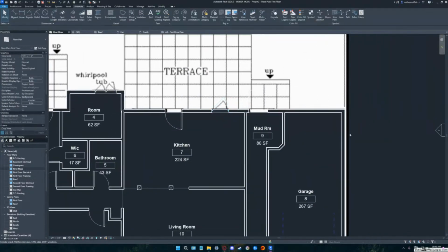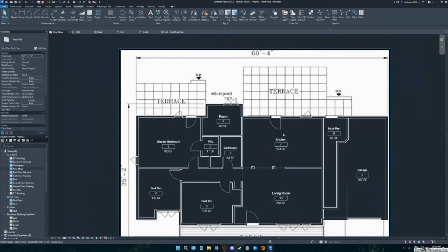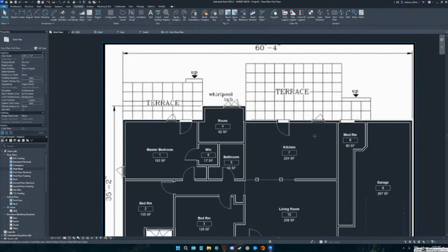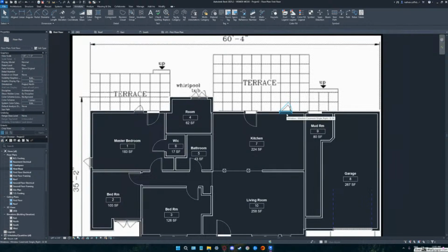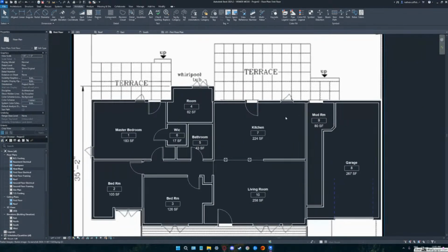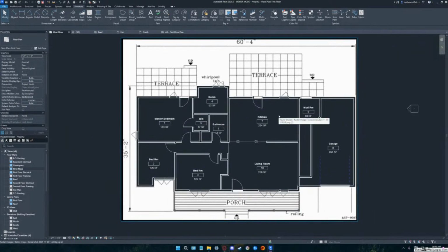That's where what we'll end up doing is when you dimension, you want to make sure that you don't have these little bugger fractions like 7/16. You make all those dimensions nice and clean. You don't necessarily have to fuss being 100% in place right now, because when you dimension it, you're going to snap on those dimensions, or you're going to snap on the pieces. You're going to see that it's 3'6" and 7/8, and you're going to clear the 7/8 out so that it's on a 2-inch. We try and keep the 2-inch increments on that kind of spacing. Okay.